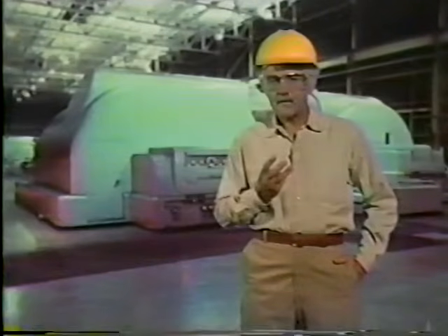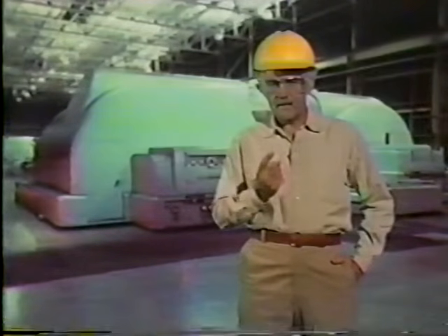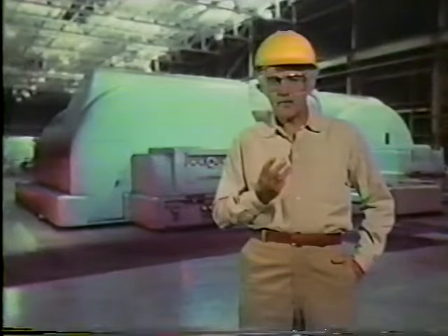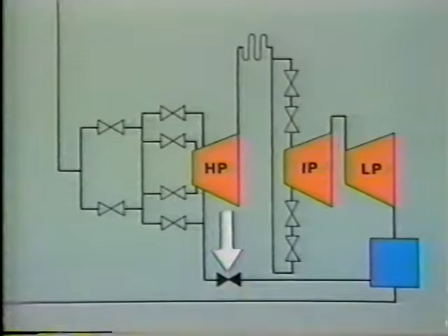The three types of valves we'll discuss are ventilator valves, emergency blowdown valves, and startup drain valves. The ventilator valve is the first type we'll look at. An important function of the ventilator valve is to prevent the turbine from overheating in the event of a turbine trip or shutdown. To understand how this valve works, let's first see how a turbine could overheat if it's tripped